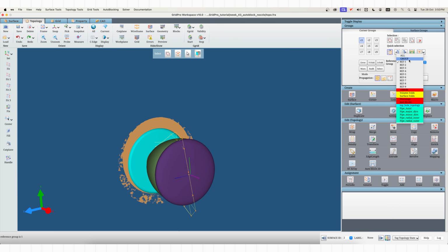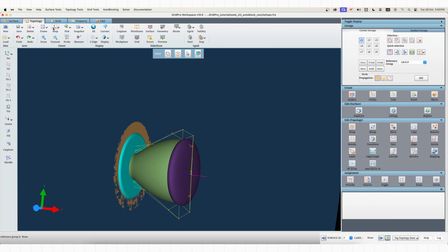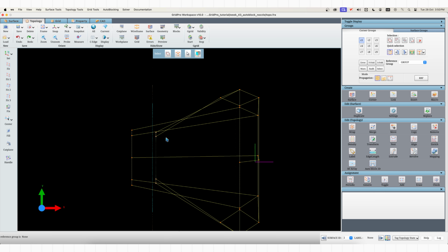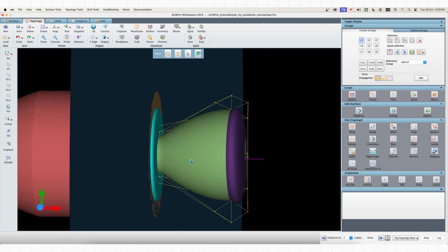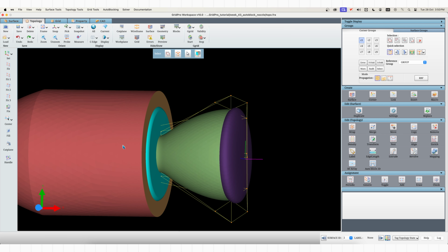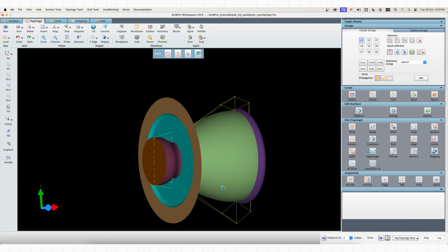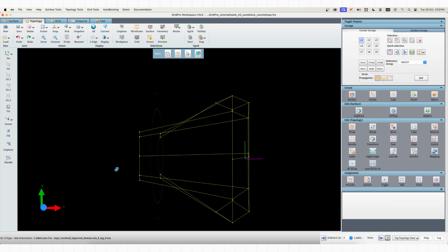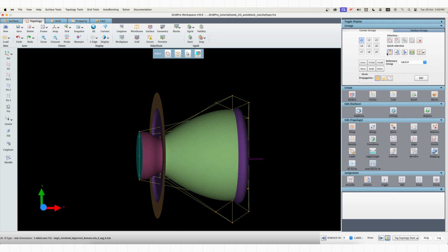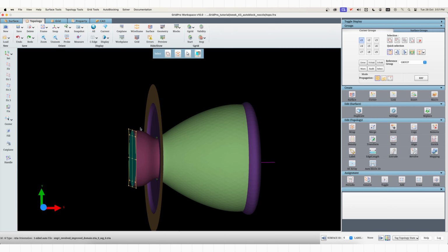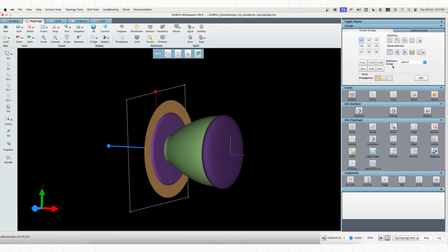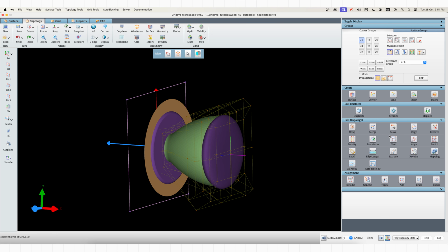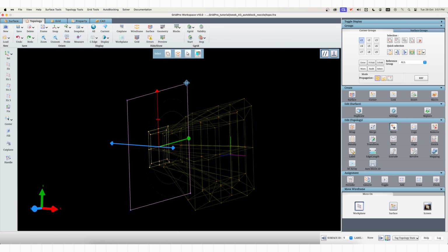Cross-section of the topology can be taken to visualize the corner positioning. Better positioning of the corners gives rapid convergence in GridPro. Let's take the corners at the nozzle inlet and pre-position them using the work plane. The Fit One option can be used to fit the work plane to the selected corner sheet, and it can be moved by clicking on the Move button to reposition the corners.